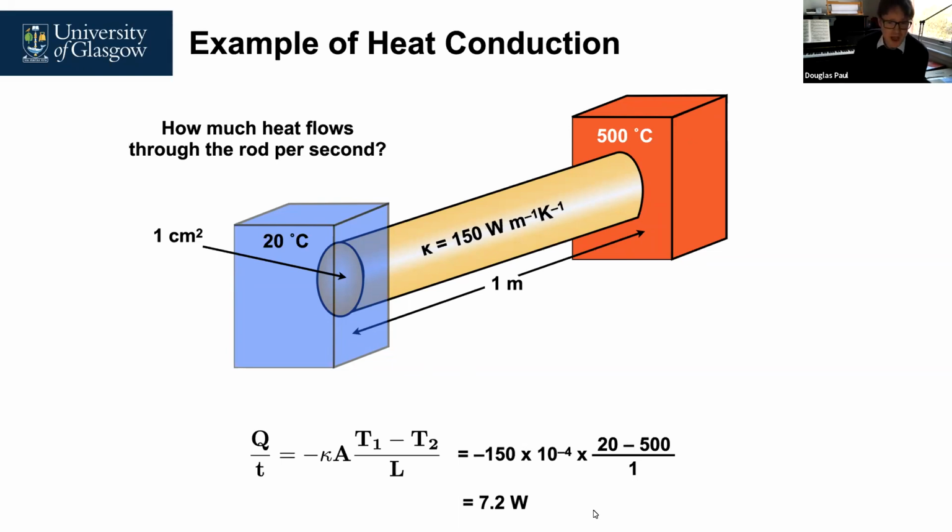So I know once you've seen the answer here, it's quite simple, but this is really something you need to worry about when you look at all the energy systems, because frequently the numbers are all in different units and you have to get everything into the same units. But the temperature is given in Celsius, so do we have to convert it into the Kelvin scale? Well, here, because it's a difference between two numbers, if you convert it into Kelvin, you're adding 273 onto both of these numbers and subtracting, they subtract to 0.